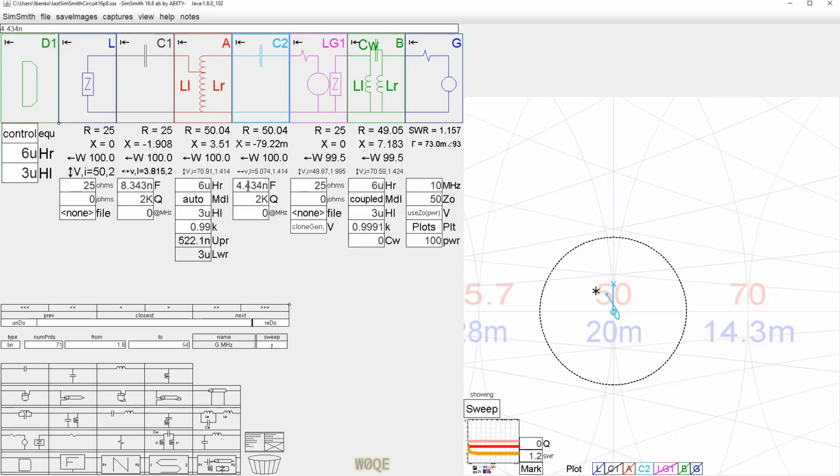And if we look at this closely, what we'll see is this capacitance value and this capacitance value should vary by about a factor of 2 because the impedance is varied by a factor of 2. This is the high impedance side, so it needs less capacitance, so it's a lower capacitance side. But now I've got pretty good performance. What can I do now? I'm willing to tolerate at the high frequencies an SWR of 1.2 to 1. Well, heck, I don't need a coefficient of coupling of 0.99 anymore. I can easily deal with a lower coefficient of coupling.